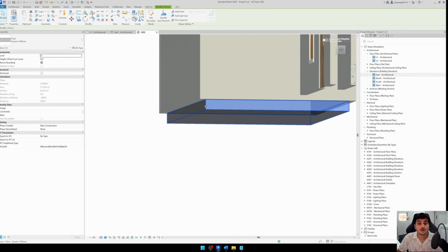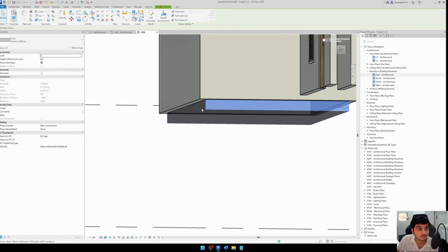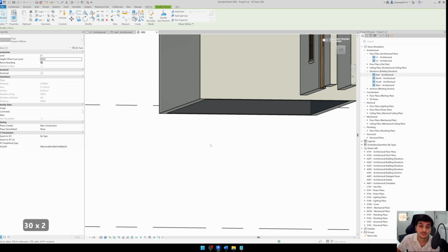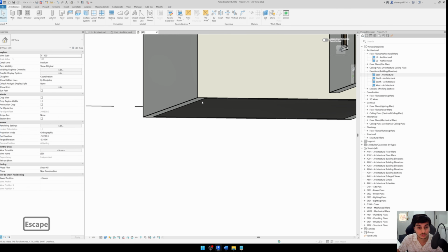Okay, now I have taken it inner to inner, so it will act as an interior floor plan. I can directly raise it to our Level 1. For example, it was of height 300 mm, so I can directly make it an offset of 300, which we usually take as 100 or else 80 mm. For now, just for your understanding, I've taken it as 300 mm. So you guys can see the floor works as an interior floor now.